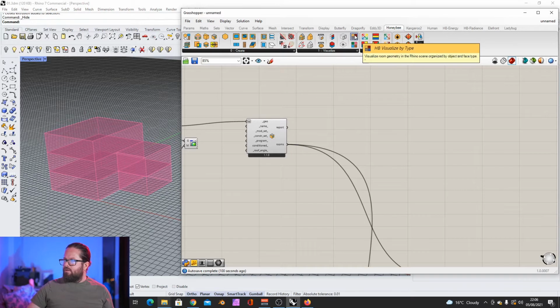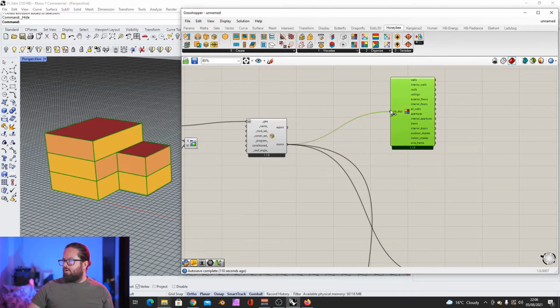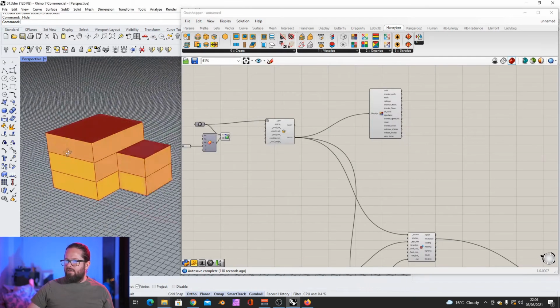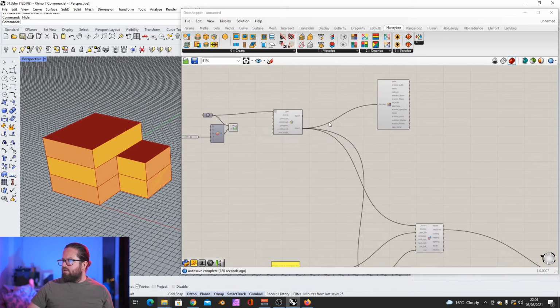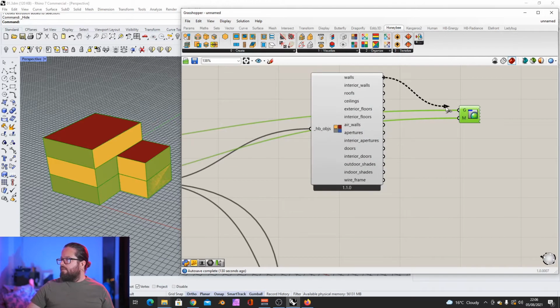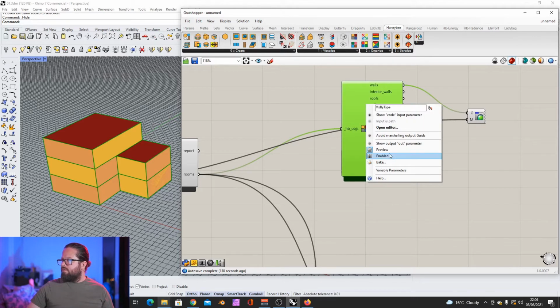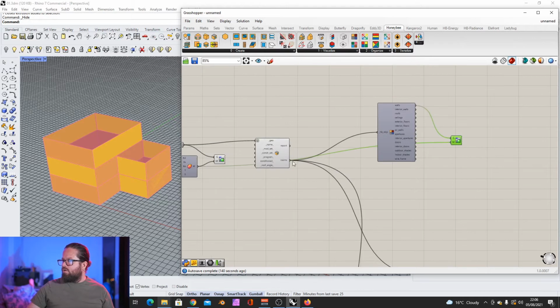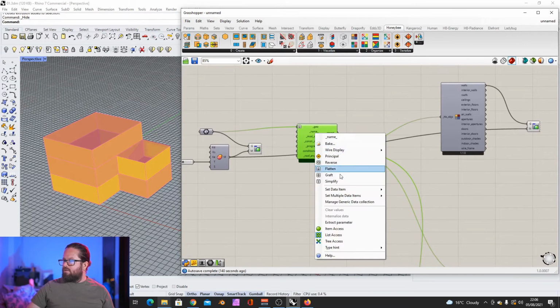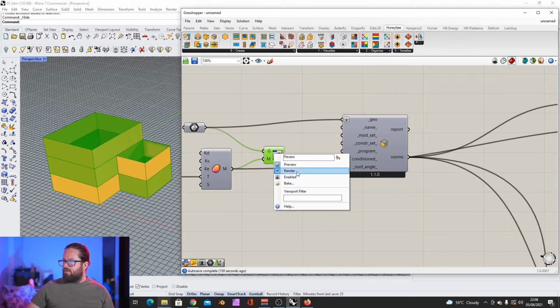open this tool here in Honeybee. Under Honeybee, the visualize by type. With that, we can plug our Honeybee objects in here, and it gives everything a color. And you can go here. We can actually use this. So if we don't want to see, let's turn this off, and then only show. I also turn, not this. This doesn't have any visual representation, but this has. So maybe let's turn this off for now.